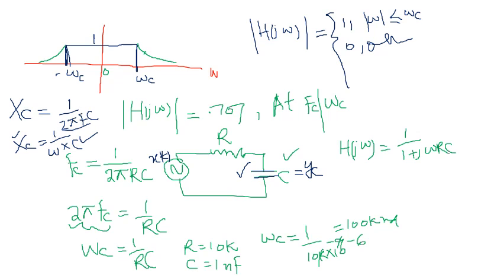Because we are taking the output voltage from the capacitor, if the voltage across the capacitor is 0, the output will have very low voltage. So I hope you understand that as the frequency increases, the capacitive reactance here decreases, resulting in reduced voltage.